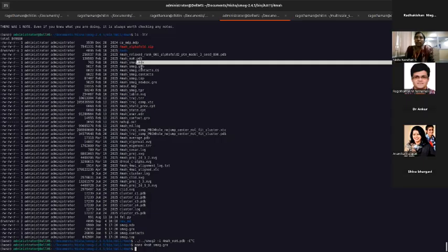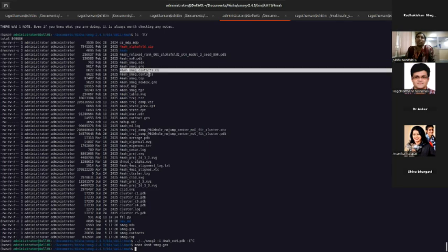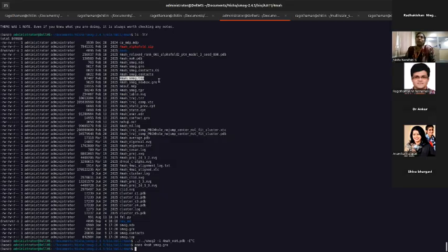The first one is the NDX file, which is the index file. It will help you trace back or map the atoms, types like hydrogen, oxygen, and also the groups, protein, solvent, ions. And this GRO file is the structure file, just like the PDB file. You can use the GRO file for simulation. And here you get two contact files. One is contact.cg, the coarse-grained contacts, but we'll not be using it in the simulation. Mostly it will be helpful for generating models other than this one. And this is also a normal all atom contacts file. Finally, it will also give you the topology file.